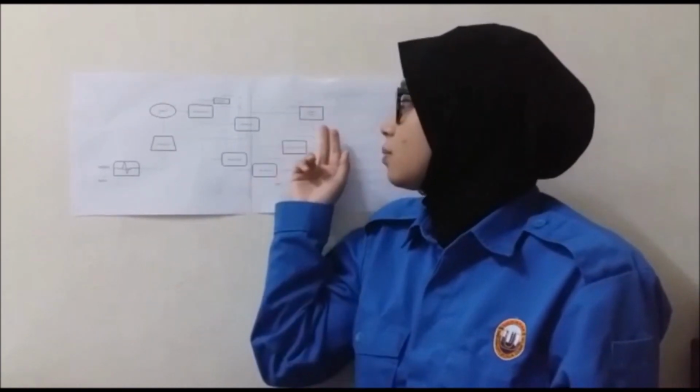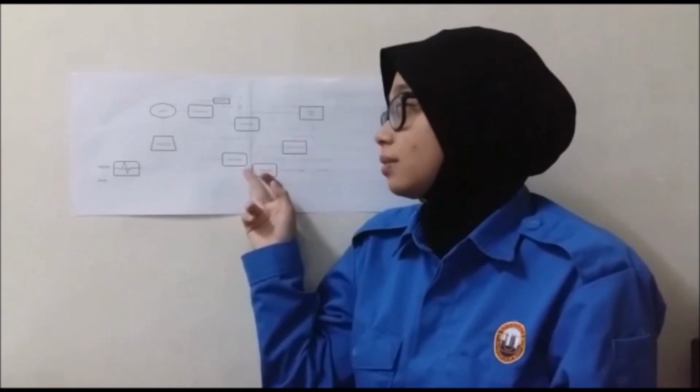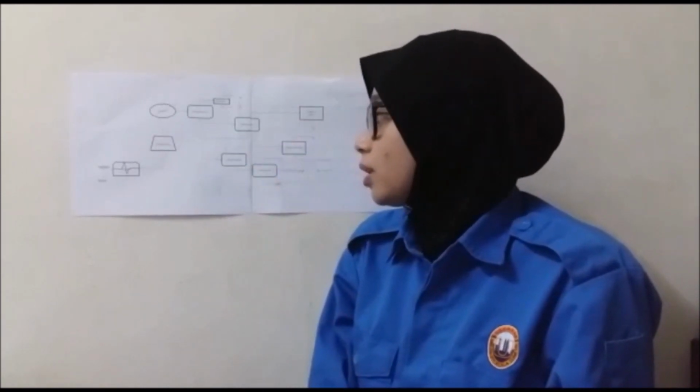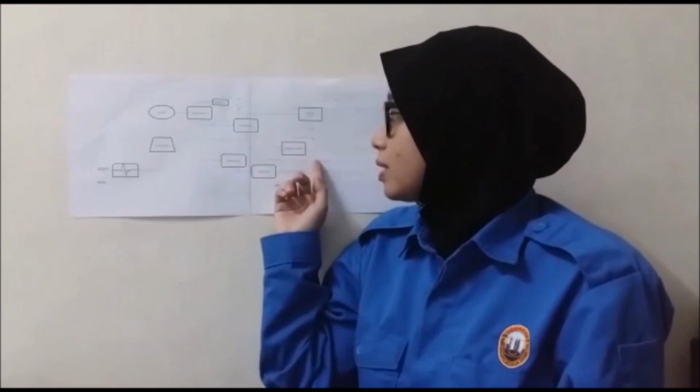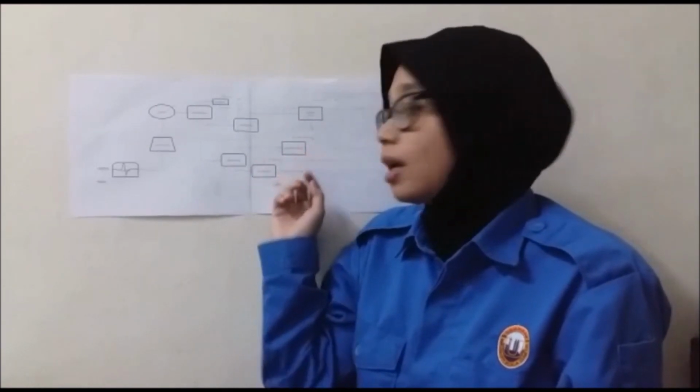Then at the deethanizer, the product will split into two: an ethylene splitter and the depropanizer. Then the product from the depropanizer will split into two distillation columns. That is the main part of this petroleum refining process. The first is a propylene splitter and the second is the debutanizer.